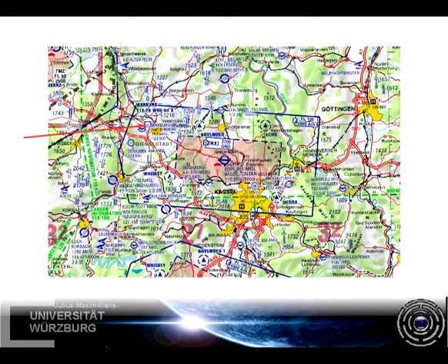Let's take a look at the VOR DME station depicted northwest of the city of Kassel. The arrows, as you have already seen in our example, can be used for drawing lines based on received radials when airborne to estimate your current position.